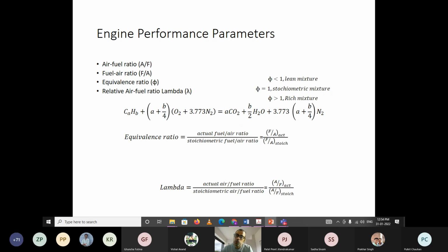But you can do the actual one anyway; it requires several other pieces of information also. We can get very close if we know the oxygen, air, fuel, air, and what the different products coming out are. Then we need some other information also, because when we are balancing the elements, the number of equations will be less than the number of unknowns. So we need some other information to calculate the products. Right now we are not going to the lean or rich mixtures.